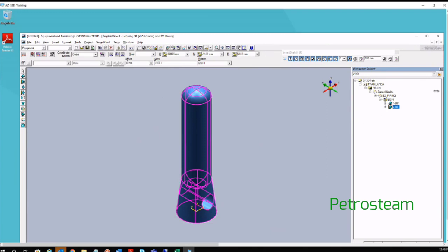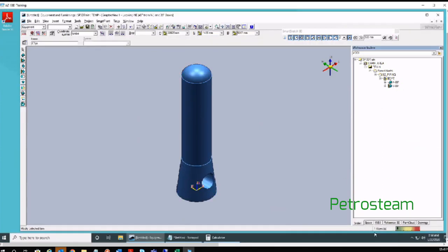If there is any error, I have already shown you how to move the reference position. Once you build the equipment, you can move its reference position. Right click, select reference coordinate system, and assume that it is somewhere outside. Right click and select the reference coordinate system. Once it is selected, enter the value and use the move command. Using the move command, you can move it wherever you want.